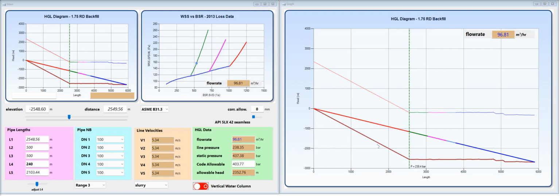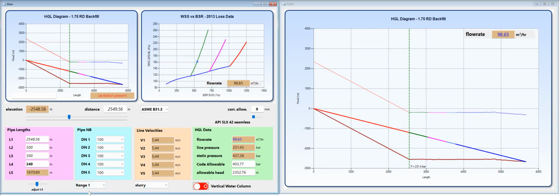This first section is a vertical column shown in 45 degrees because the height and the length are the same, and here's your horizontal run of pipe to the different ranges. Have a look at the flow rate here as I change the range routes. As it gets shorter, the flow rate will increase. As it gets longer, there's more resistance. The flow rate drops.